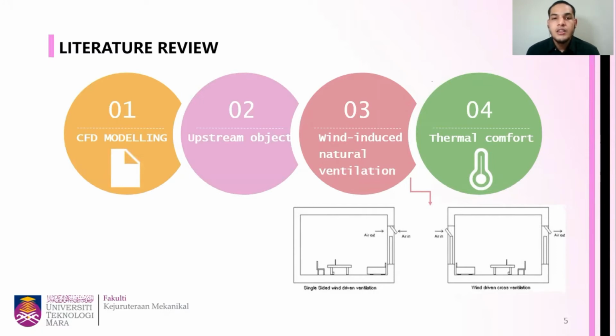For number 3, we have wind-induced natural ventilation. Natural ventilation can be further classified according to the mechanism. The driving force for the wind-driven mechanism is pressure difference, and as the pressure difference increases, the rate of airflow increases. The airflow rate also depends upon the area of opening. Natural ventilation caused by the wind is a passive way of enhancing the interior atmosphere and occupant comfort.